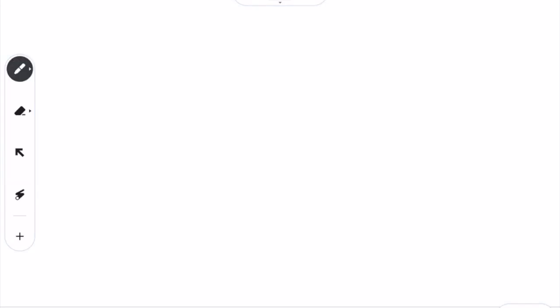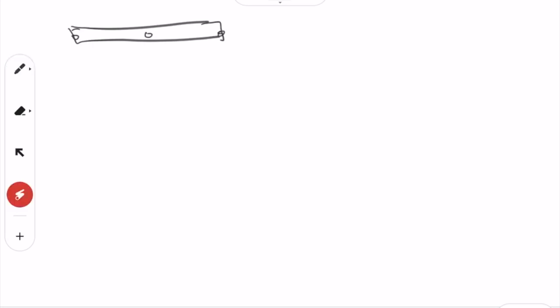If you see here, this is symmetric. You can imagine this as: K11 is nothing but, if you fix this and you free this one and apply a unit displacement, whatever forces are there will be the stiffnesses. So this will be K11, the force you require to introduce a unit displacement, then the reaction force here will be K12, and the reaction force here will be K13.